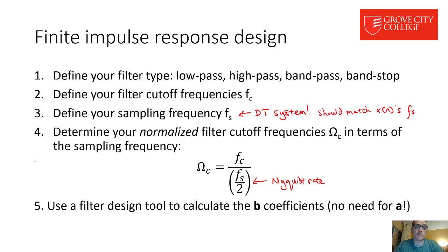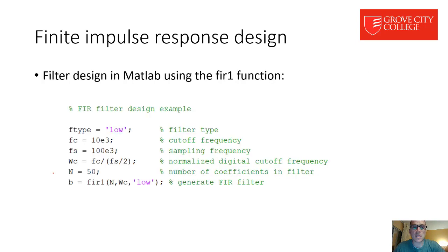We're not going to do any by hand filter design. There's so many great tools out there. We're just going to use tools built into MATLAB to do the calculations for us. Okay, so here's how to do the filter design in MATLAB. This is a function called FIR1, and this is as simple as it gets to start with.